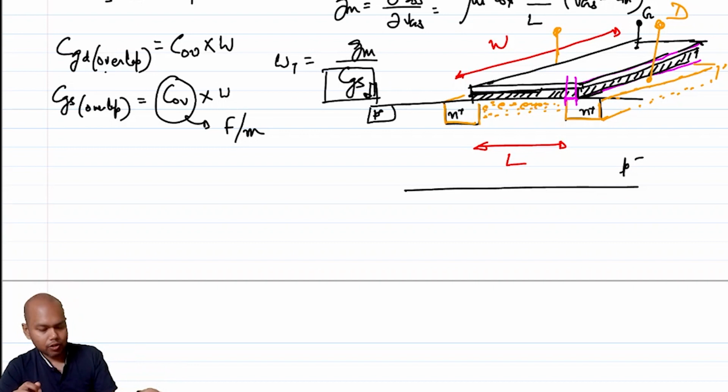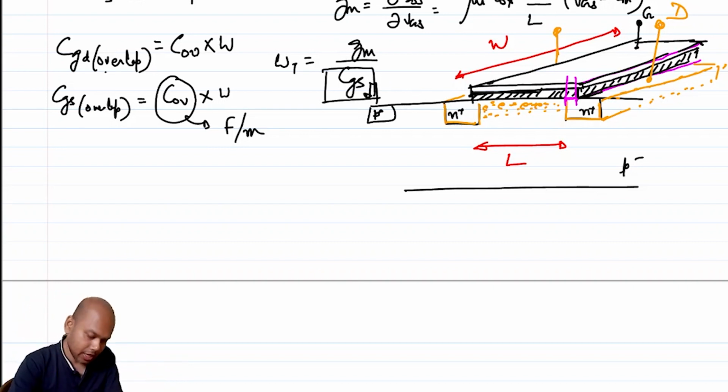Now let's focus on the fact that your transistor is in saturation, and let's say it is in saturation in such a way that you have just reached pinch off. It's a long channel device, and you have reached pinch off. It's not the correct way to draw the pinch off condition. So you have electrons here, it's filled with electrons. So now what is happening is, this is all electrons.